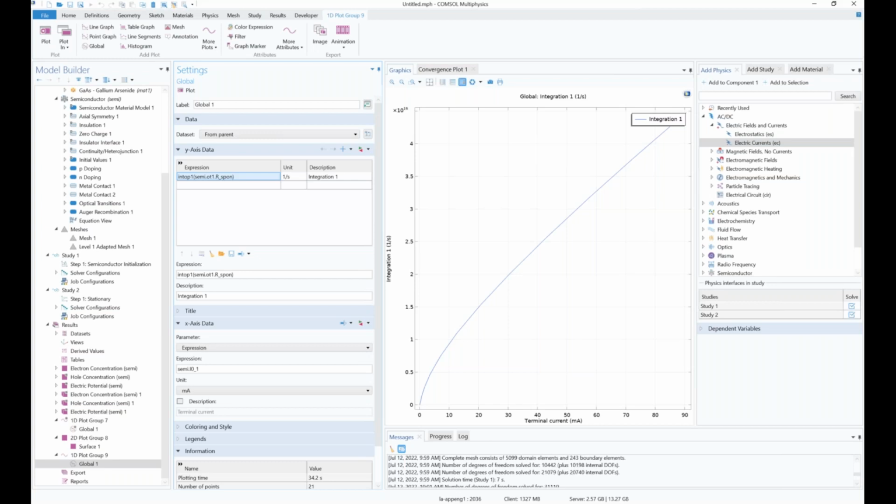When you have those band structures and you know all those band gaps of your materials, you can use drift diffusion, which is the classical way, and Schrödinger, which is quantum. So with drift diffusion, we consider those electrons and holes as carriers. They're moving, transport under a drift. Drift is driven by the field.